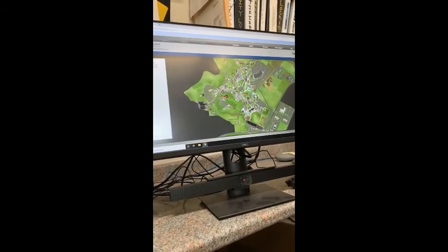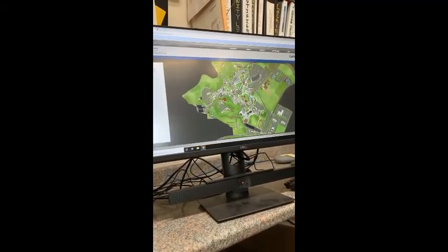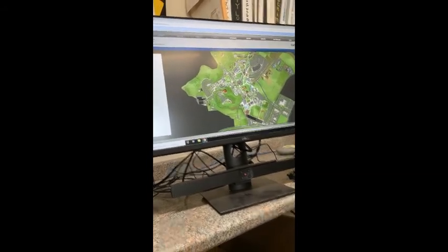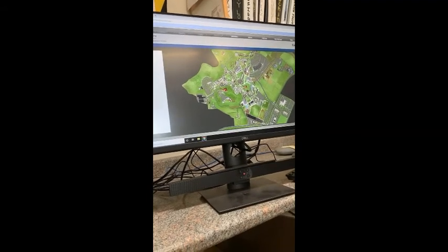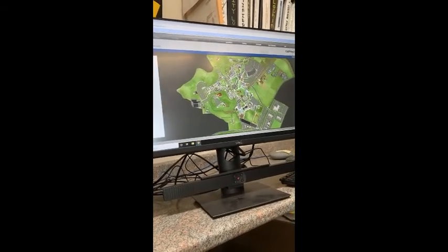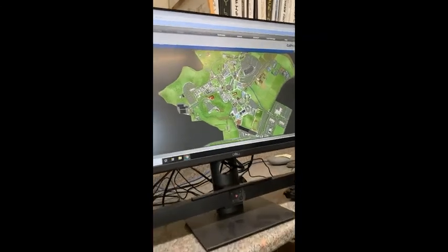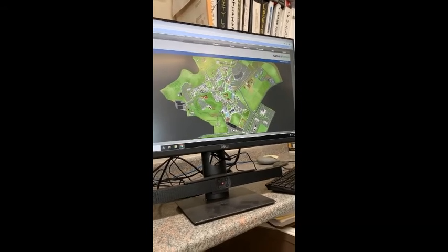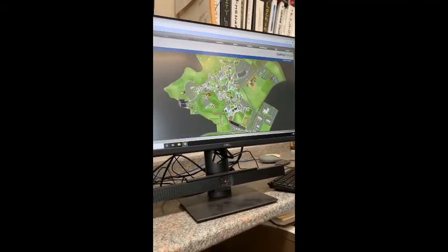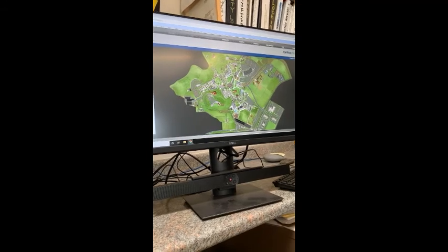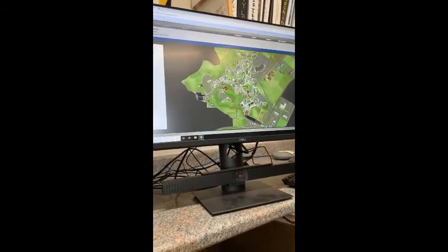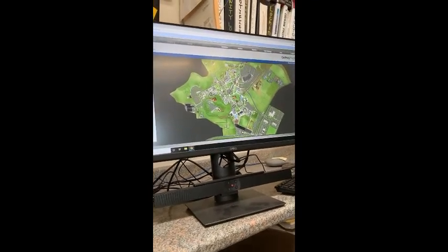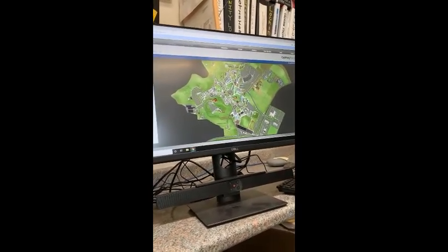Basically what we have here, this system is looking over 3 buildings, the dining hall and the 2 new student buildings. It is all one system. The way the system works is this computer works as the supervisor or the server, and through the IT network, it talks to what we call Supervisory Controllers, or JACEs. There are 5 JACEs in each of the student buildings, and 2 in the dining hall.